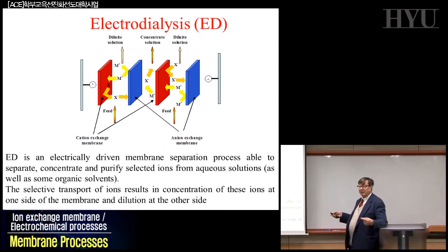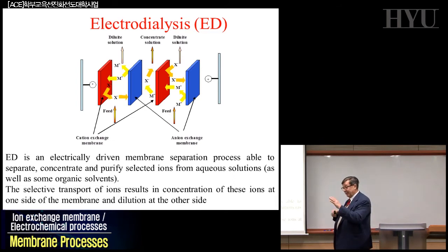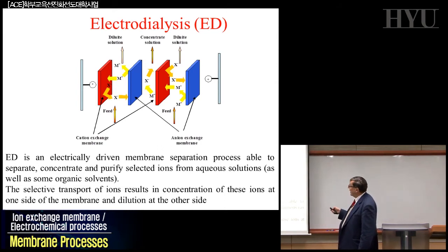So most part of the artificial milk is produced through membrane operation, in which you selectively remove some salts so that you approach as much as possible the same concentration that you have in natural products. So that gives you an idea of what can be done here. You can separate selectively, depending on the perm-selectivity of the membranes, removing the ions from any substance where you want to keep concentration at a certain value. So this is basically the electrodialysis, and we will see that this system is useful in this way.